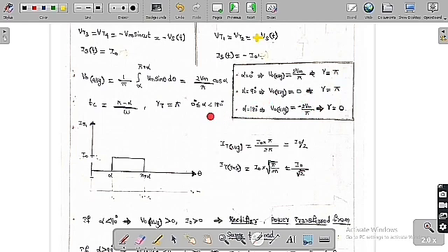So here, the conduction angle of the thyristor is independent of alpha up to here. Whereas at 180 degrees, it is going to become 0, meaning they are not going to conduct at all. Therefore, it is equal to 0. So from 0 to 90 degrees, the average value is always positive, whereas from 90 to 180, the average value of the output voltage is negative.